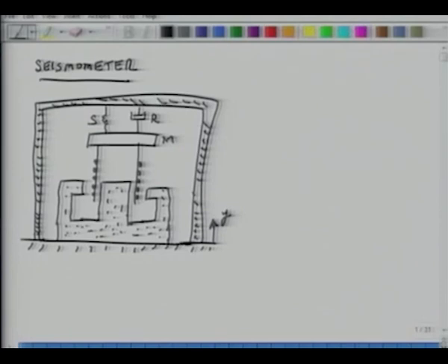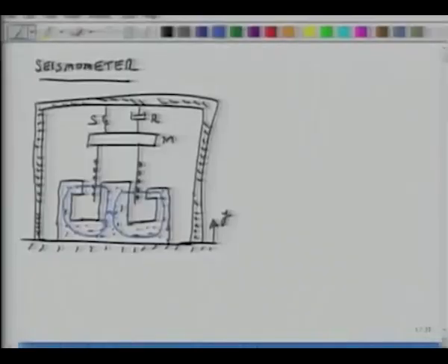So what you have here is that through this motor structure, magnetic flux cuts, I mean, this is how magnetic flux moves. And it cuts the conductor, which is wound around a bobbin, that is the coil, and that induces motion in the coil. And because of vibrations, the coil moves relative to this magnet, and that induces voltage. And we connect it to an external voltmeter and sense the vibrations.